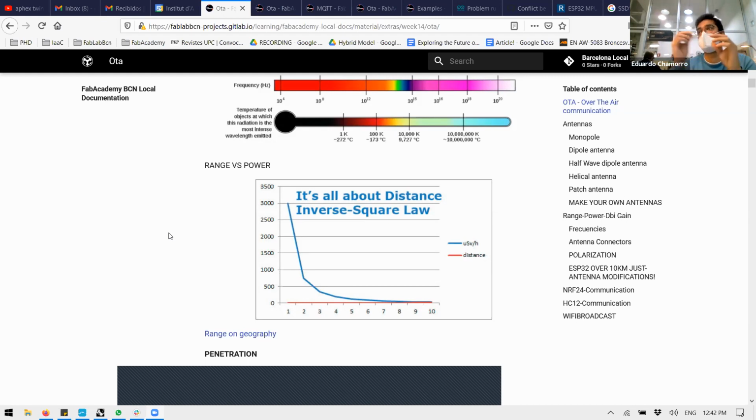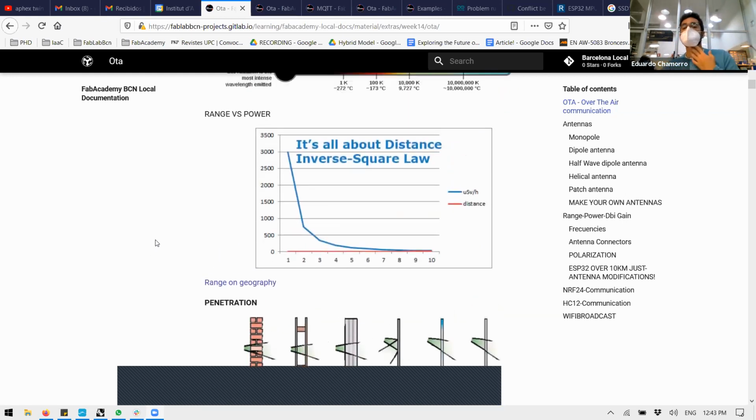So for example, the paper base is less dense, it is lighter. You can see on the weight that it influences the frequency absorption of the copper layer that is attached to it. Simply put, the wavelength passes on the copper and then penetrates easier into the paper than into the epoxy. The epoxy has a bit of refraction, so the tuning of the antenna is different.